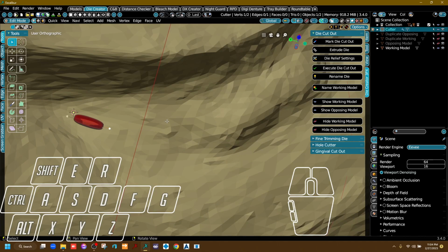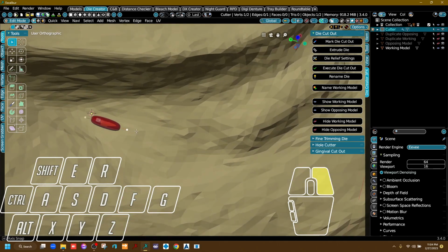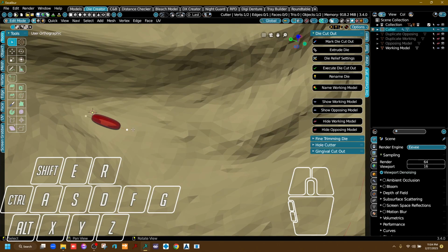Instead, we have to extrude this line that we're generating essentially and build it all the way around. A lot of people compare this step to, like, an inchworm or a caterpillar or something like that. You'll see what I mean. So it's kind of fun, but it does take some time to get used to. So the first thing you keep in mind is all the keyboard shortcuts I've been going over. G for grab, you know, and in this case, we're going to add one in, and that's E for extrude.